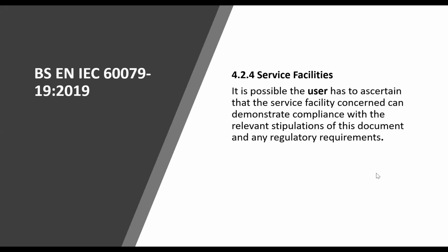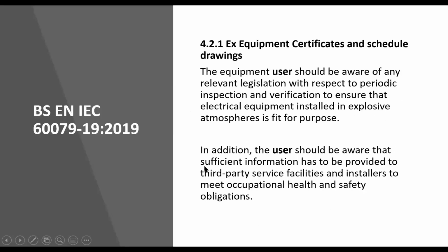The user has that responsibility. If the user isn't asking for that information, then the repair facility doesn't have to give it to them. If an incident happens, it is the user's problem. The user has to explain why they have fitted a piece of hazardous area equipment into a hazardous zone, not knowing the full specifications of that job, not knowing that the measurements were taken, not knowing what standard it was repaired to, not knowing that the repairer was competent or been on any training courses. This is all the user's responsibility. This is what people don't understand.